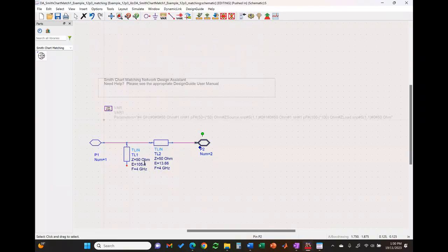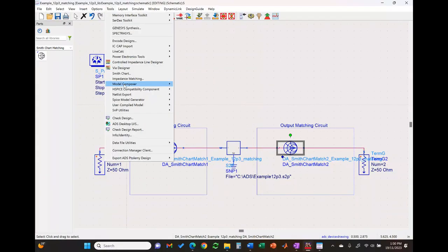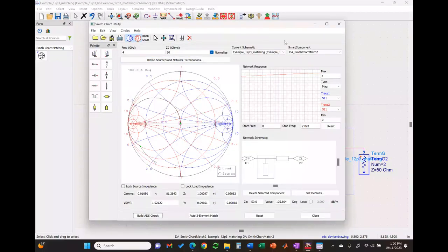So now if I go in here, okay. So this is your open circuit stub circuit for the first case. Okay, I think this is one of the solutions again, because we always have two solutions. So if I go up now, let me save this. Now you do the same thing for the load side. For the load side, again, go to Tools, Smith chart.